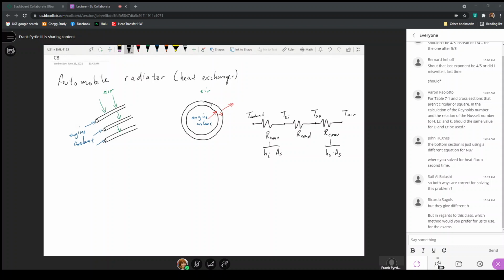So we get an average heat transfer coefficient on the outside, and that will be my h sub o. In chapter 8, we'll go through, well, how do I get an average heat transfer coefficient for fluid that is actually flowing through the pipe? And of course, here for the resistance due to conduction, this would be the natural log of the outer radius over the inner radius divided by 2 pi times k times L for the conduction resistance.